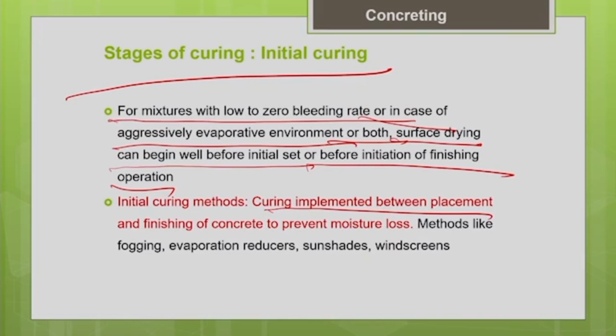I cannot apply water, but I can go for some windshades or sunscreens, or I can do fogging, or I can spray the evaporation reducer chemicals on the surface of the concrete. These are just done to prevent the rate of evaporation from the surface of the concrete. This is called initial curing because we can do it even before the start of the finishing operation.